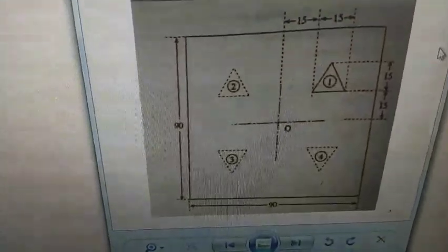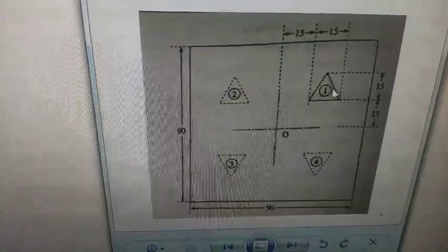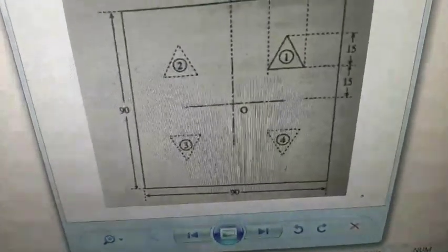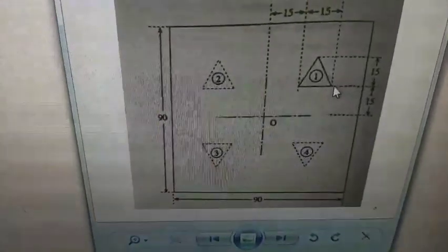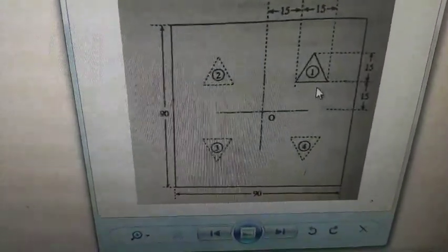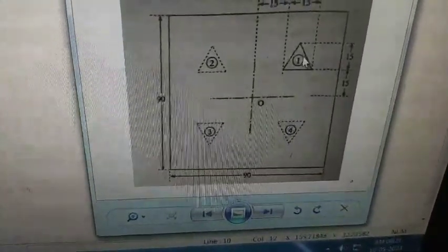So this point, see my mouse is here, this becomes x 22.5, y is 30. From here it will come here again, so x will become 30 and y is 15. So I wrote in the next line the x30 and y15. So this point is x30 and y15. The same holds for all these objects: same dimensions, symmetrical dimensions, and the figure is also symmetrical, shape and dimensions both are symmetrical. So I can use the mirror command. So I use mirror M70, M80, M71, x and y.